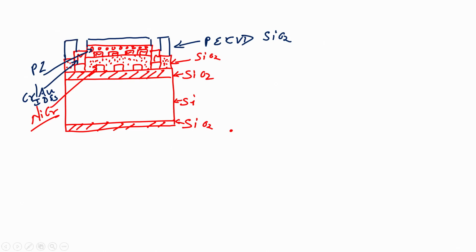If you understand what are the ohmic contact and rectifying contact, you will understand why the thickness of the metal is important or is related to the contact. Now, over this, because we want a gold pad, we will deposit gold using PVD, physical vapor deposition. When I say gold, it is assumed that there is a thin layer of chrome below gold, right.